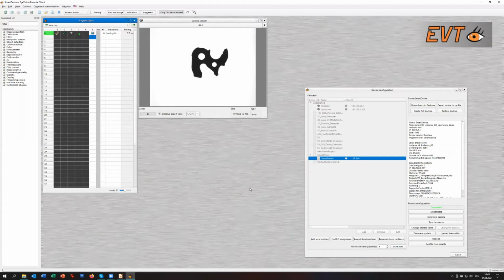So to have a feeling if your solution works on the smart camera, you can simply have a look at the timing at the end and see if you are as fast as your process needs. From our experience, for most of the processes, if you do the standard gray and color image evaluation, up to 10 parts per second can be done with smart cameras, depending on the instructions that you need.